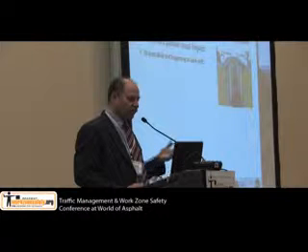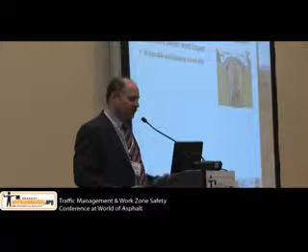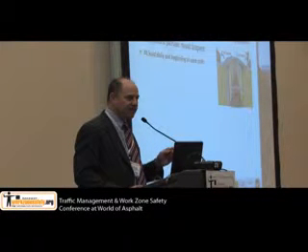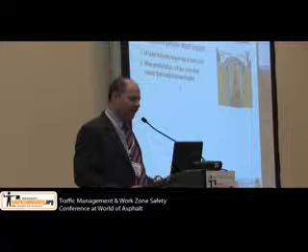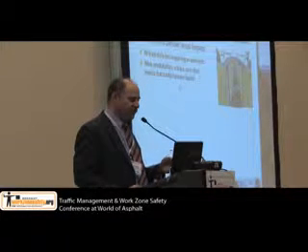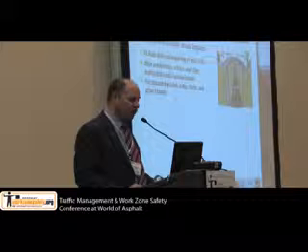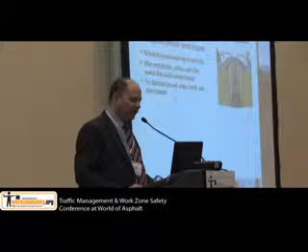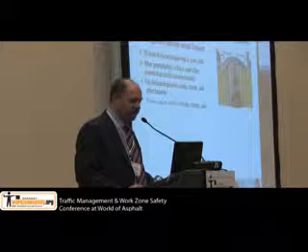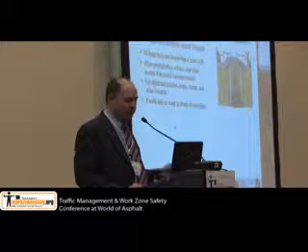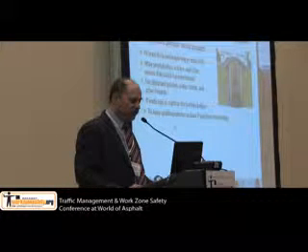And this is what the responsibilities of the competent person are: to do an inspection at least daily and at the beginning of every shift, and after there's been precipitation or a thaw. They look for any disturbed ground, water, toxics, or other hazards, and for walls sagging, cracking, or bulging.